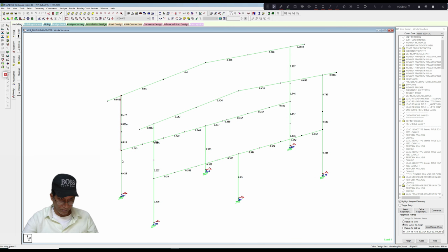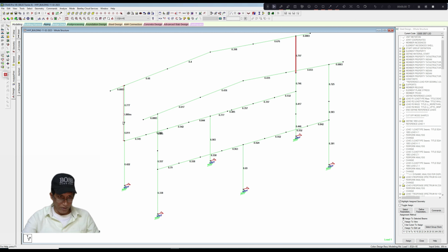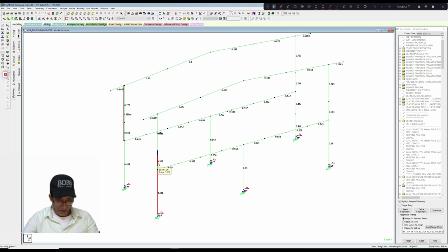Now see, this column doesn't have a possibility of any optimization because it's 0.8 and 0.77 is at the top. So for the sake of example, we will design a splice connection here. For this column also, the top part is critical, the bottom part we have already taken minimum sizes, so we could